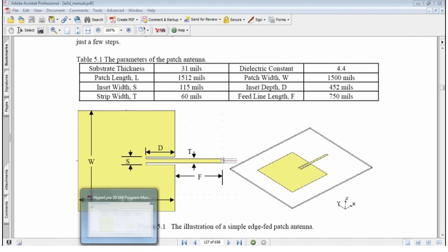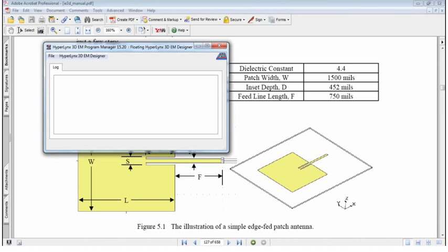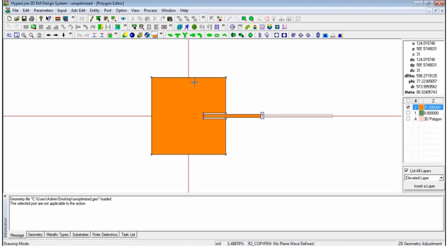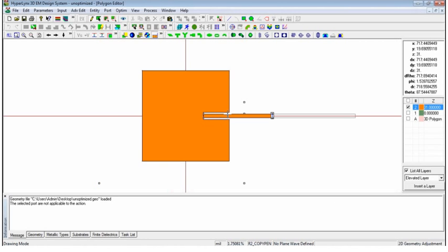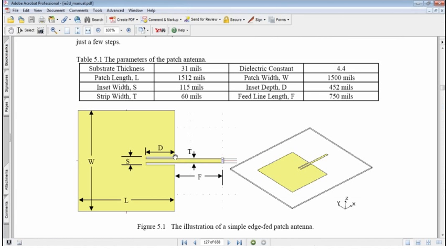we have already created a structure here in IE3D. So this is the structure. As I said, if you control the depth of this antenna, the D parameter here, we can control the impedance matching. Whenever the antenna resonates at that particular point, the impedance should be 50 ohms.